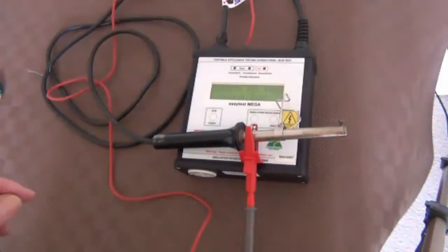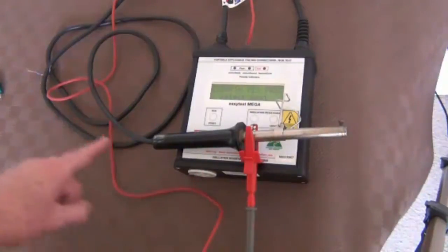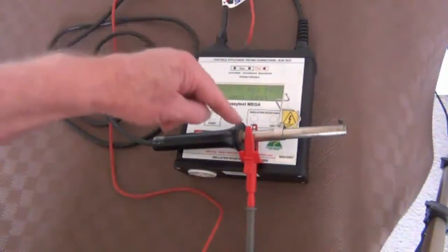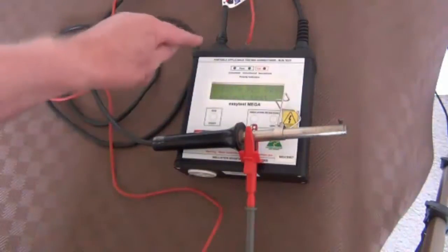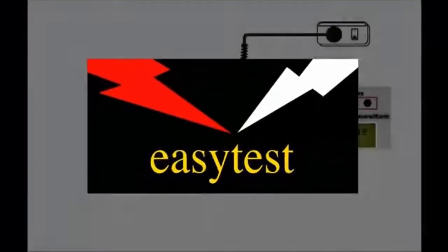I'll just turn that off because it's starting to get fairly warm. And that's something you have to be very careful of when you're doing this test, that it will be in its normal operating condition. So that's the main difference between the earth leakage test and the insulation resistance test. In the earth leakage test, we are measuring the current leaking through the insulation in the unit, back through the earth wire. And in the insulation resistance test, we are putting the insulation under stress and trying to blow a hole in it.